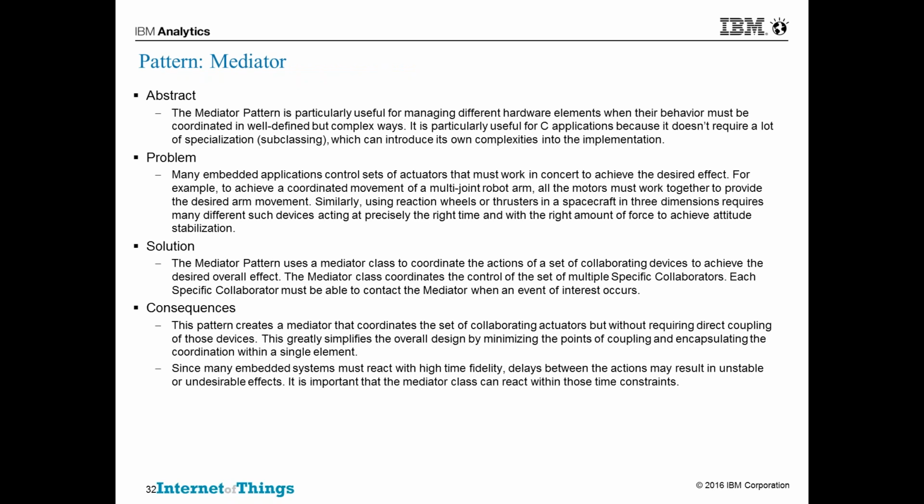Another pattern I use a lot in complex control systems, particularly robotics, is the Mediator pattern. Mediator pattern is when you want to manage a bunch of different elements in coordinated and well-defined ways. But those well-defined ways might still be complex. Now you could arguably have all these elements talk to each other and have a group therapy session about it, but often it's useful to have a mediator which takes this high-level task and allocates those tasks in a sequenced fashion to smaller elements to perform the work. And that's what the mediator basically does.